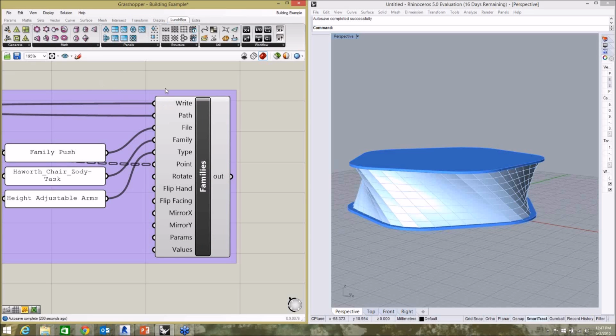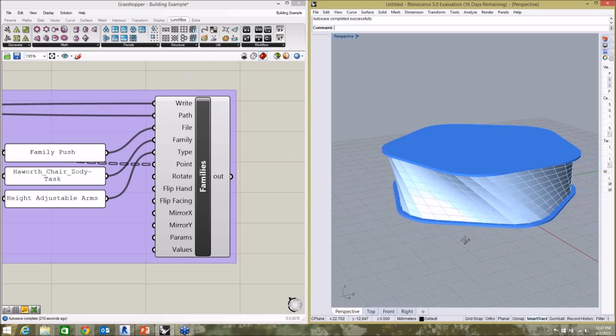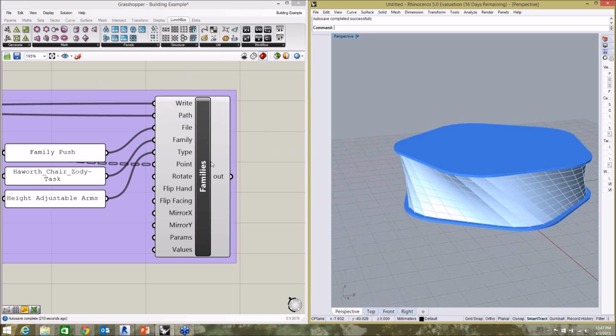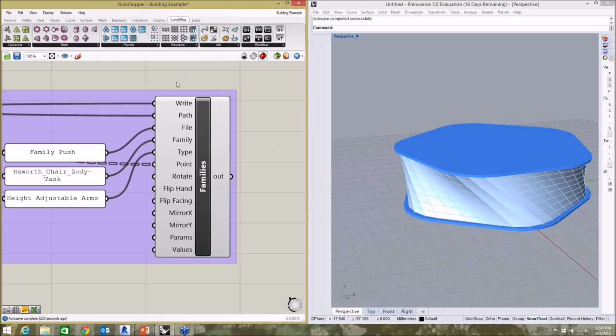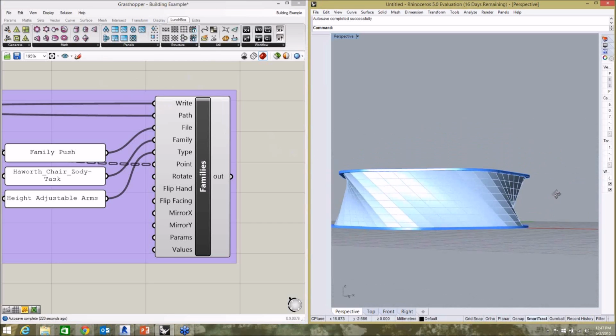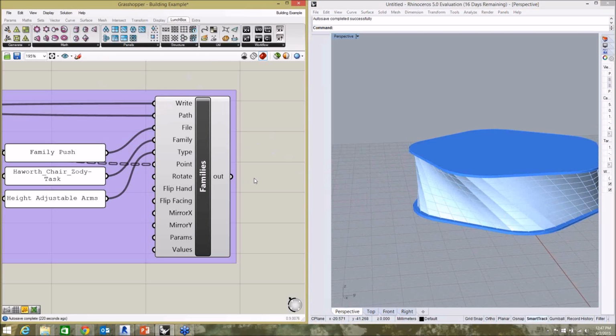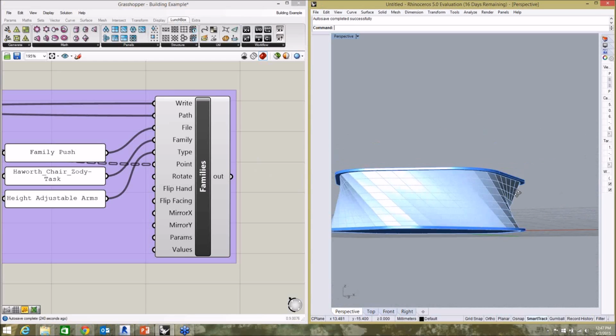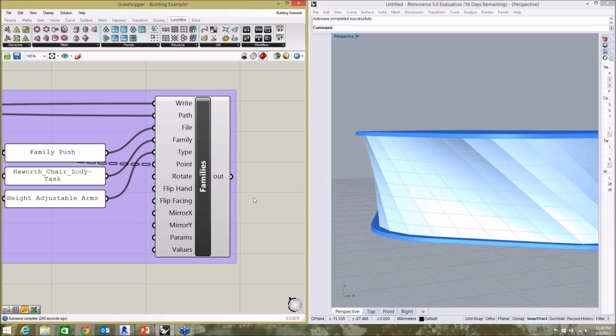All right. Another thing I want to give kudos to is the Lunchbox tool utility created by Nathan Miller. That one is what I use to divide the surface for this project. I don't want to use that tool without giving a good shout out to Mr. Nate. So thanks, Nathan, for developing this. It's really slick for dividing surfaces. There's also some other really great utilities out there that I don't have in here for this webinar, but you can actually create planar panels so that you don't have this twisty glass, which is essentially not buildable. You can actually create planar objects, and maybe I'll show that in the next webinar.